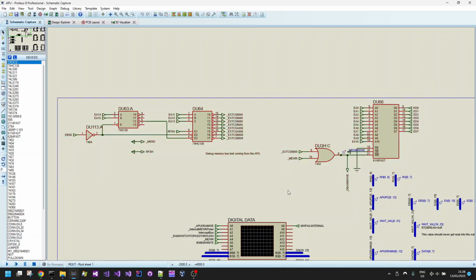So it's using exactly the same parts with exactly the same timings. So I'm making sure that, at least for this memory range, which is actually the sprites memory range, writes to the sprites memory range would actually flow through to the video hardware correctly without needing to import the full video hardware schematic. And I can also do other tests.